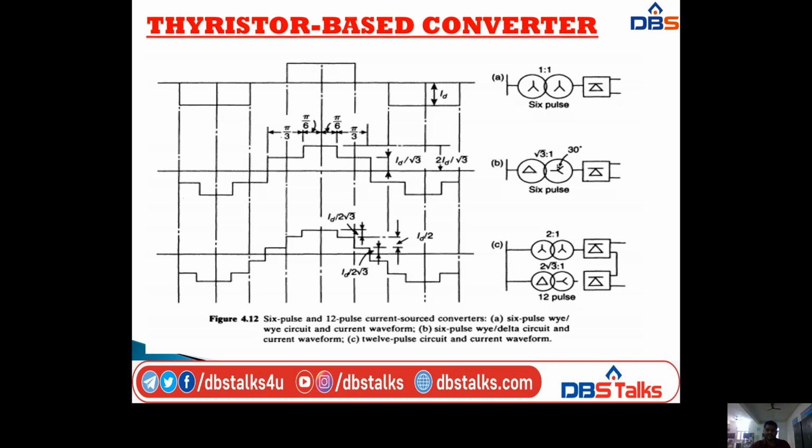Next, this is the waveform. So actually this gives the 6 pulse and 12 pulse current source converters. First diagram gives the 6 pulse star to star connection, circuit and current waveforms. On the right side we have the circuit and on the left side we have the waveforms. The second diagram gives the 6 pulse star delta circuit and current waveforms. And the third one gives the 12 pulse circuit and current waveforms.